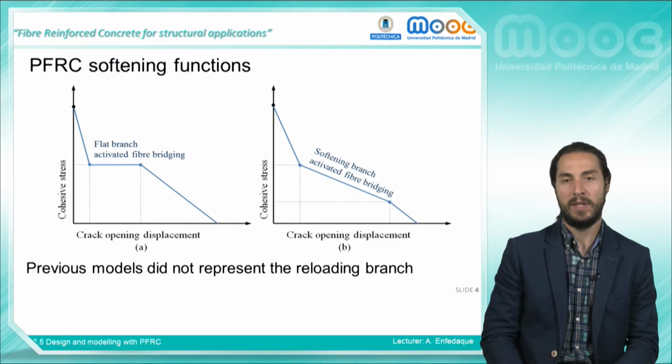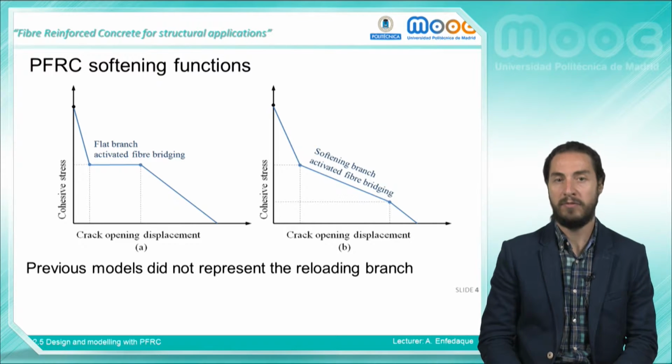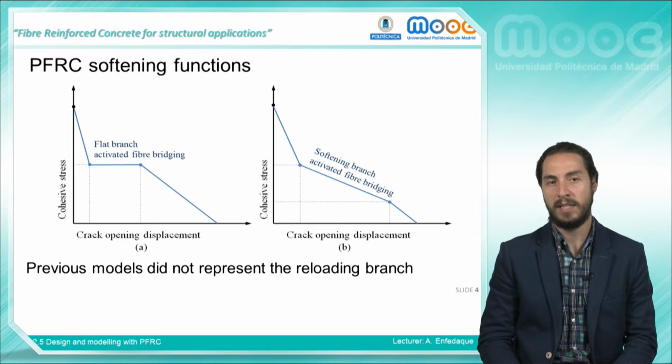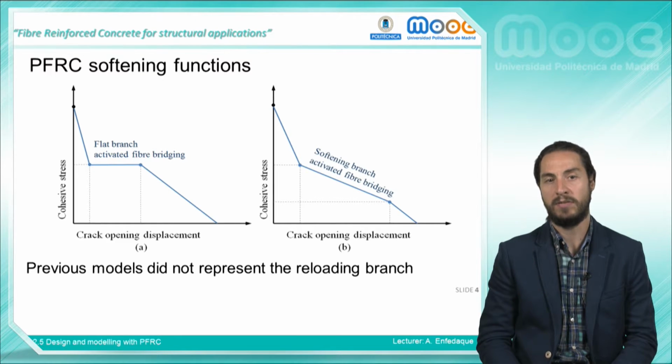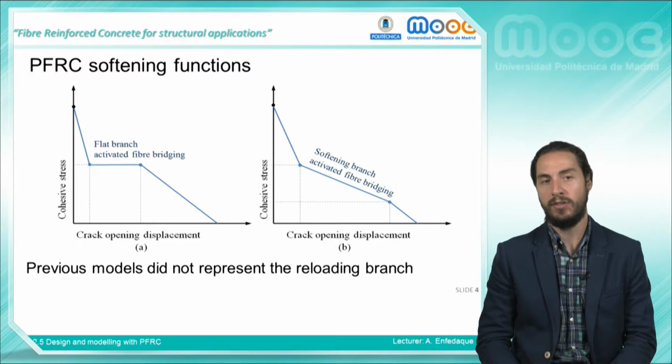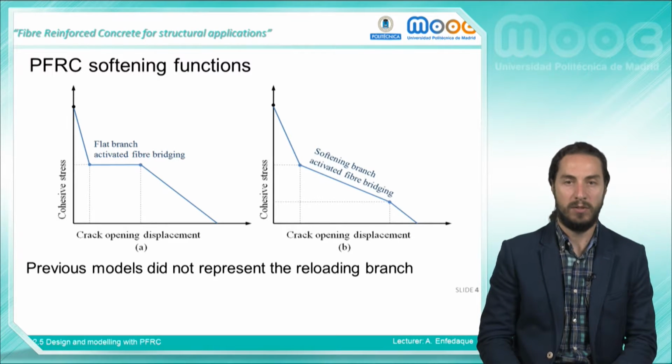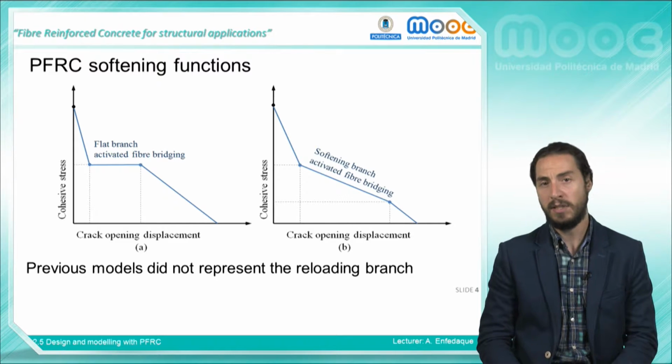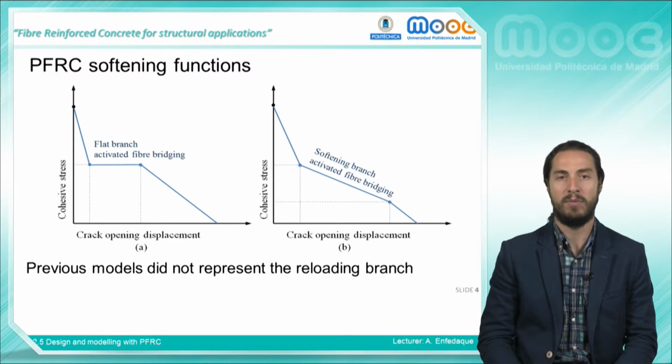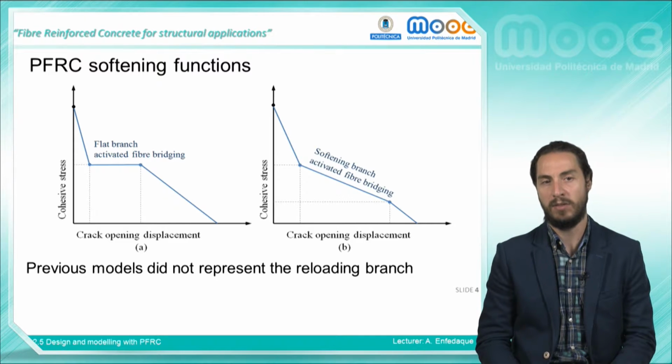Moving to modeling the mechanical behavior of polyolefin fiber reinforced concrete, it has to be said that traditionally some of the most used softening functions applied to fiber reinforced concrete have been built by joining straight lines with several slopes. Up to now, the main differences were established in the second zone, which differs from a slope of 0 to a negative slope.